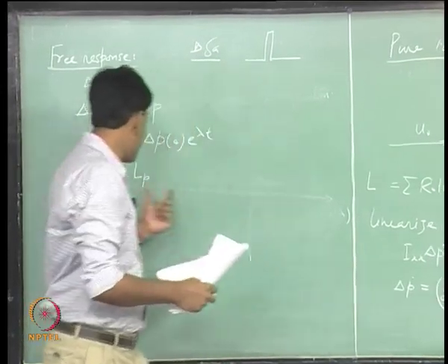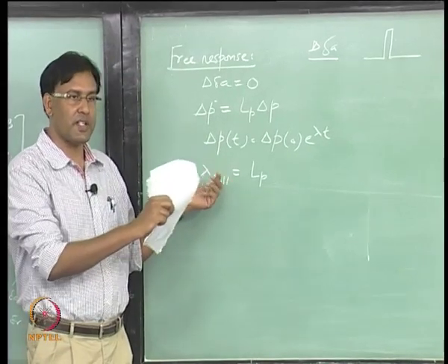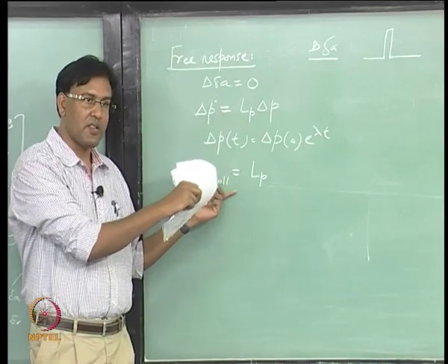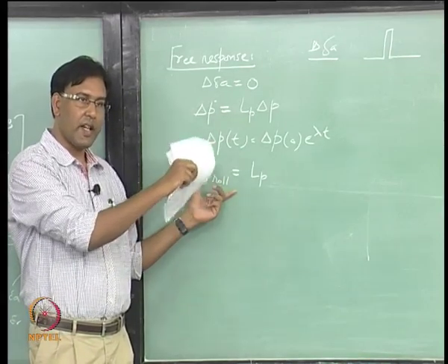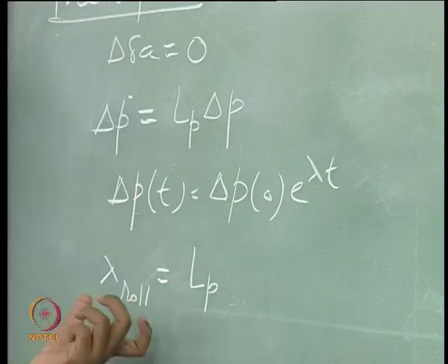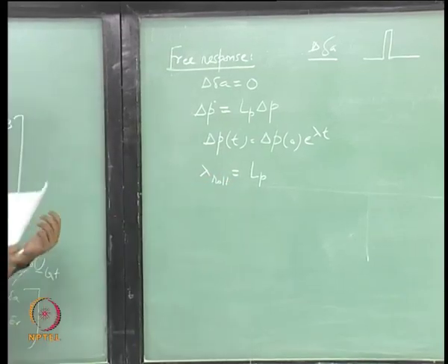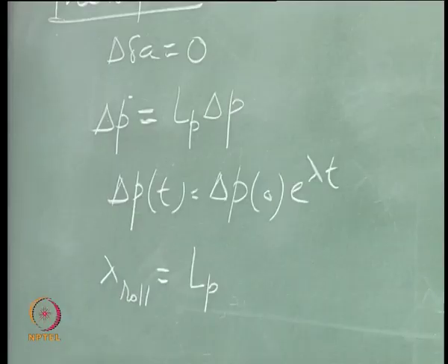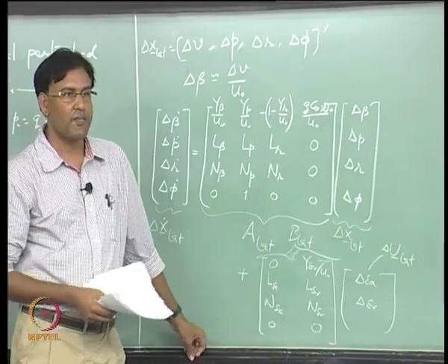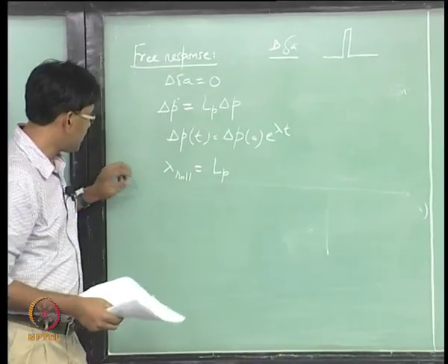Because now you are able to extract one eigenvalue, this may be a rough estimate and sometimes very good estimate actually. In case of roll, actually this is a good estimate. You are able to get this one eigenvalue, and once you have this eigenvalue, now you are only left with a cubic equation, right, which you can solve and find out other eigenvalues. So, that is one advantage.